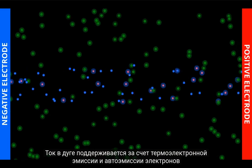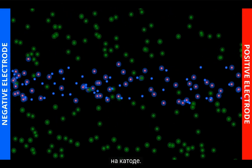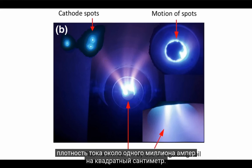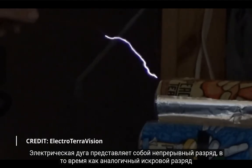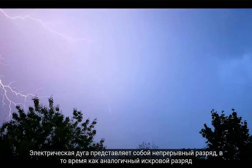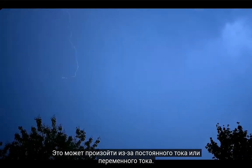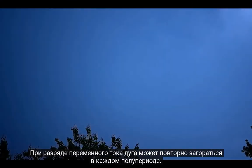The current in the arc is sustained by thermionic emissions and field emissions of the electrons at the cathode. The current may be concentrated in a very small hot spot on the cathode. Current densities of around 1 million amps per square centimetre can exist. An electric arc is a continuous discharge, while the similar electric spark discharge is momentary. It can occur due to a direct current or an alternating current. In an AC discharge, the arc may restrike on each half cycle.